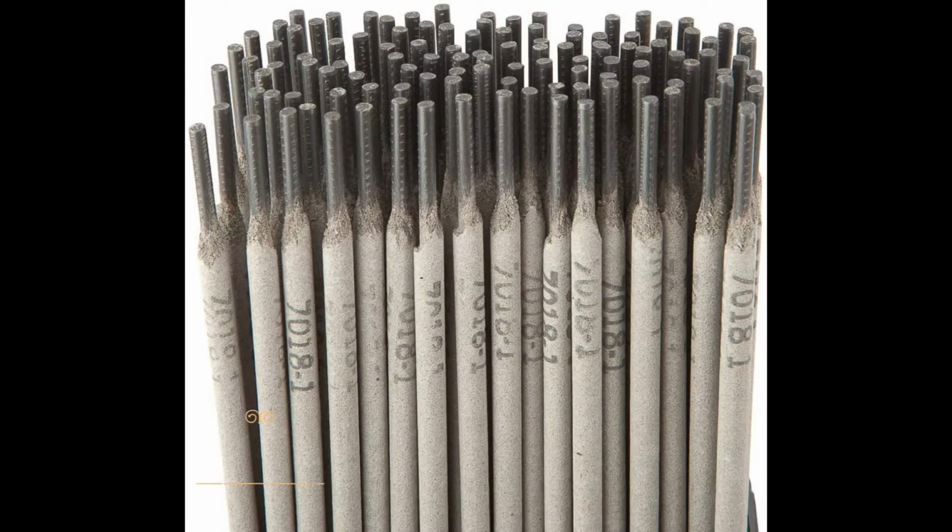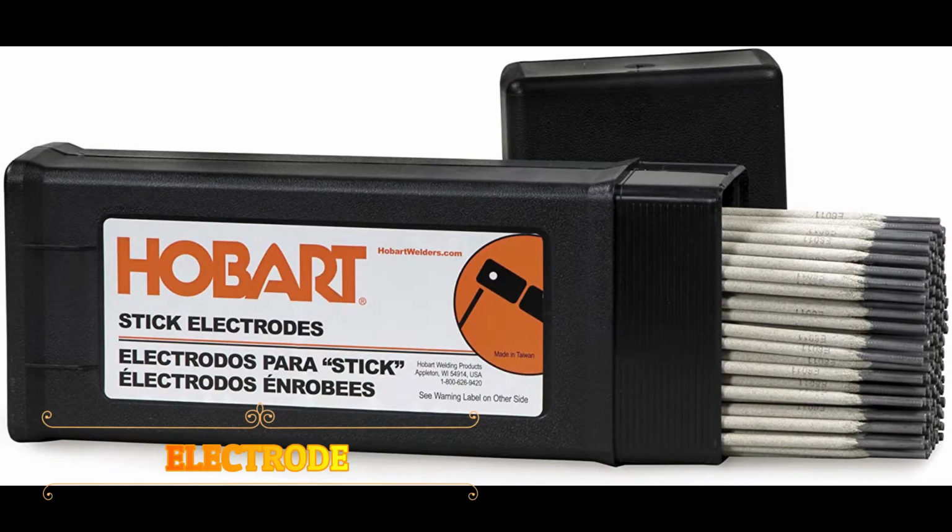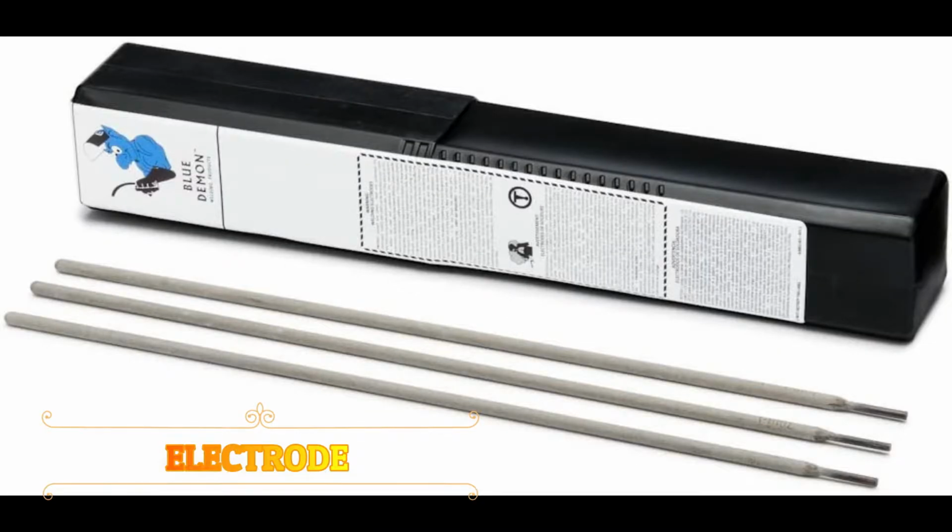The next one is welding electrodes. An electrode is a piece of wire or a rod of a metal or alloy with or without coatings. An arc is set up between electrode and workpiece. Welding electrodes are classified into mainly two, consumable electrodes and non-consumable electrodes.